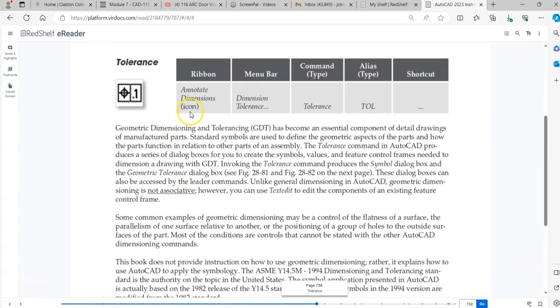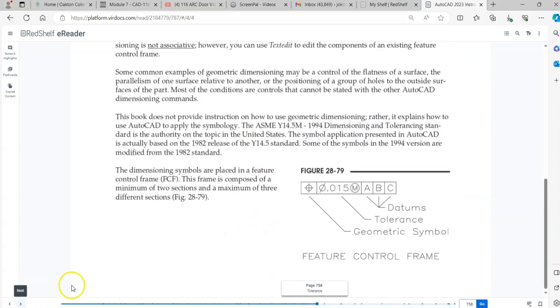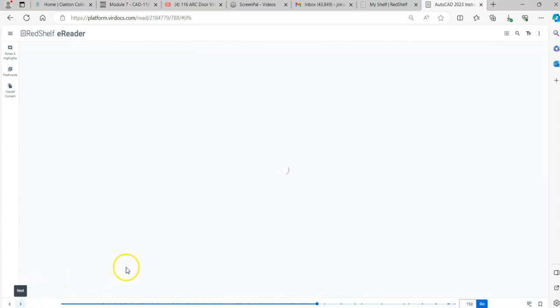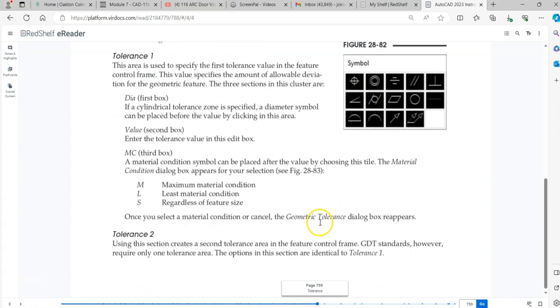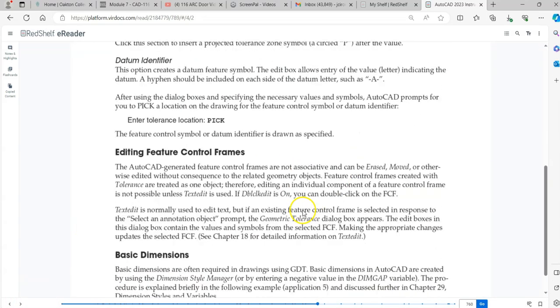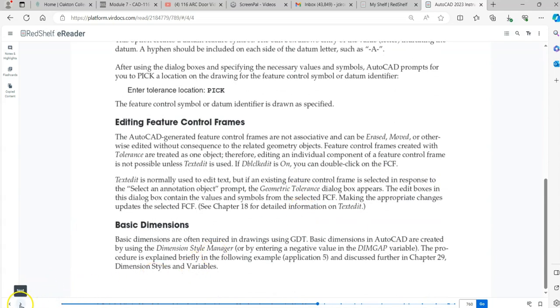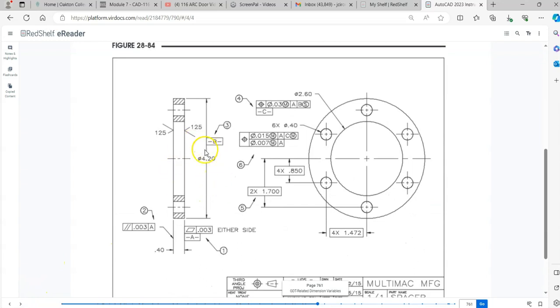And then we can add tolerances as well. And so as we progress through the course and get better at designing, we can start to create dimensions that have meanings like how much flatness or diameter relationships, tolerances, meaning how accurate that component needs to be. Things like maximum material conditions. And this is a somewhat advanced feature of CAD as we start to work on creating these drawings.